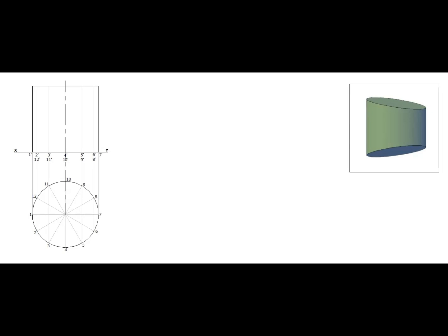At the right-hand side, mark 15 mm from the bottom end, and draw the cutting plane through this point and the left-hand side corner. For the second cutting plane, mark 15 mm from the top end. Join this point to the top corner at the left-hand side. These are the two cutting planes. Mark points wherever the cutting plane cuts the reference lines.